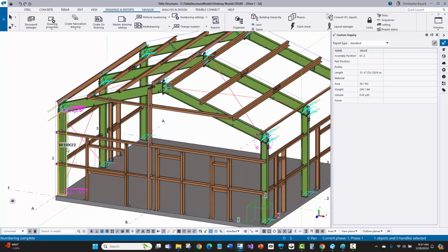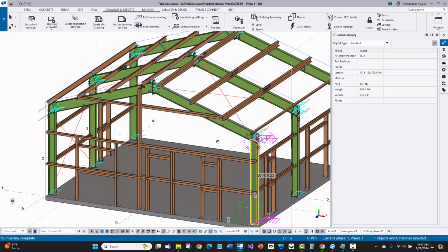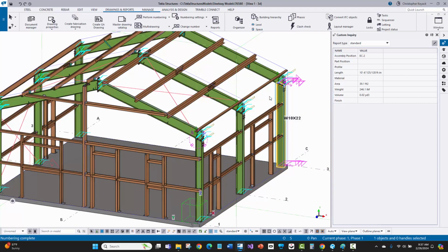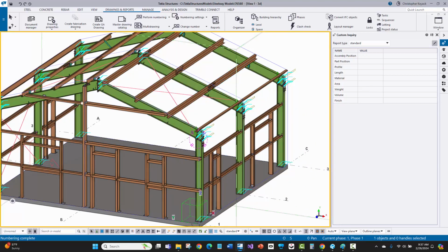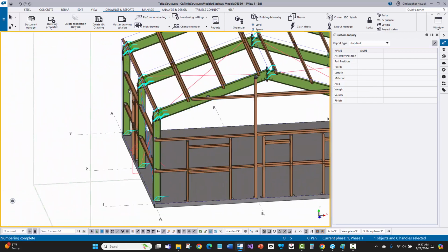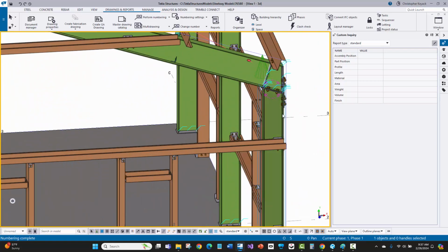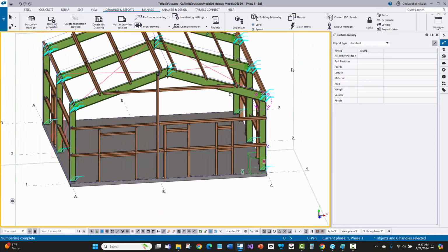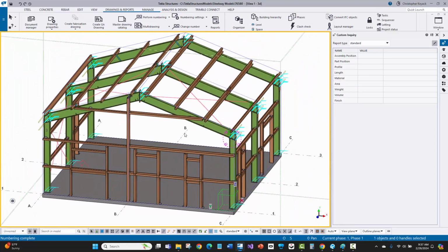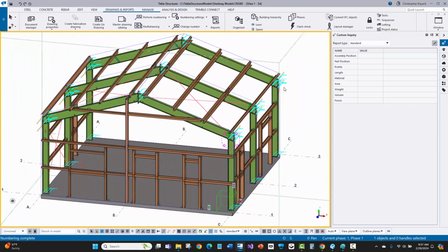Now let's look at the columns. So we've got EC3, EC3, EC3, and then over here EC2, EC2, and EC2. These are different here because on one wall it looks like rod bracing, and we've got those slots in there, and then on the other side the slots are not there, so that's why the columns are different. But what does matter is that all of the columns along that line and the rafters along each line here are consistent on each side of the building.